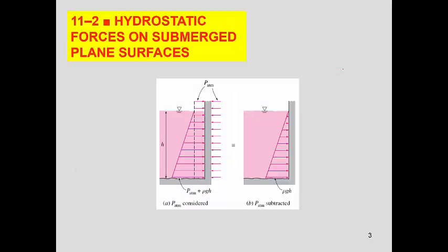And what we'll look at is submerged plates that are vertical, and it can be a plate or it can be a wall. What's important to recognize is that the hydrostatic pressure, which is due to water, even if the wall is very, very high, starts where the water starts. So this is 0, and you have a triangular distribution, like a line, P equals rho g h with intercept equals 0. If you look at the form of this equation, mx plus b, this is the slope, this is your x, and then 0 intercept.